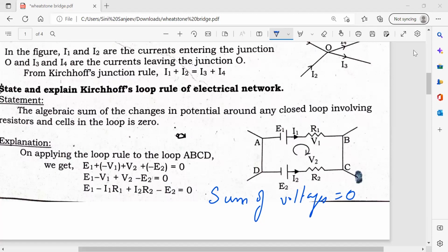So this, if I want to write here, what is the keyword here? Sum of all voltages is equal to 0. Correct? And here I can see the voltage is in clockwise direction. And this is my negative terminal, minus plus. Correct? Minus plus. And for all the resistors in all the problems, whenever it is in clockwise,